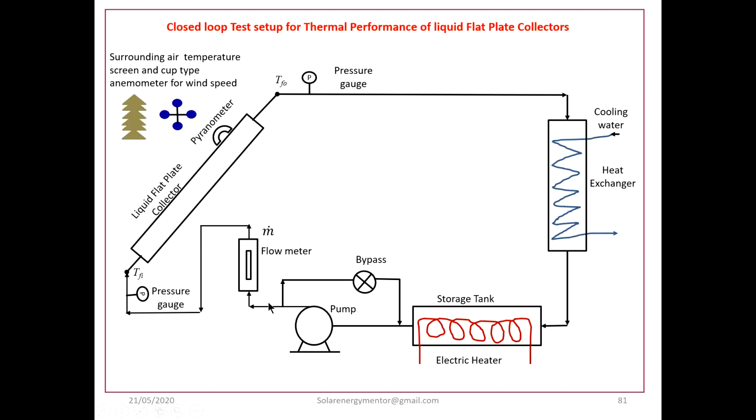When he closes the valve, pressure builds up on the back side of the pipe, and the pressure goes on building, which damages the pump, valves, and fittings. The same thing will happen if the discharge is to be increased: there will be a sudden increase of pressure that may damage the line. To reduce that effect, a bypass valve is used, which can be opened widely or closed.